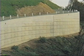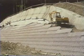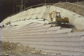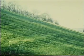As a generalization, hard facings are used in the construction of vertical walls or very steep slopes, while wrapped facings are used mostly for slopes with angles between 45 and 70 degrees. Caged facings are typically inclined at 60 degrees to the horizontal. Flatter slopes may not warrant a facing, but are vegetated to protect against erosion.